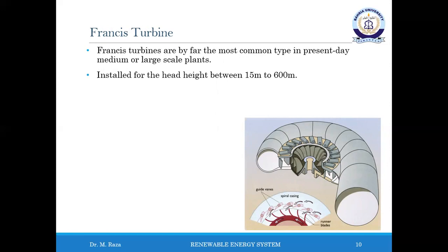Advantages of reaction turbine are as follows. It requires less installation space, that is, runners are smaller than Pelton turbine. It provides a greater net head and better protection against the downstream high flood level because it can run submerged. It offers greater runner speed. It offers high efficiency for higher power values.